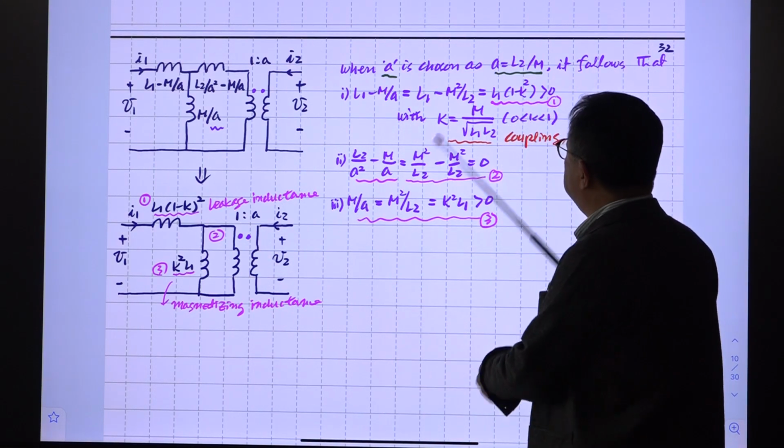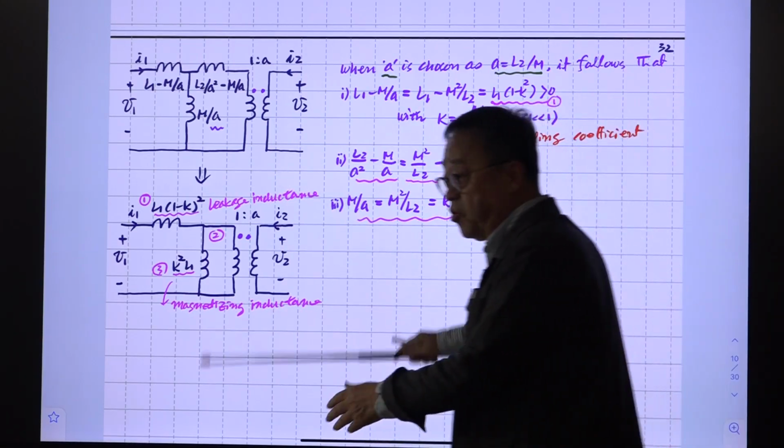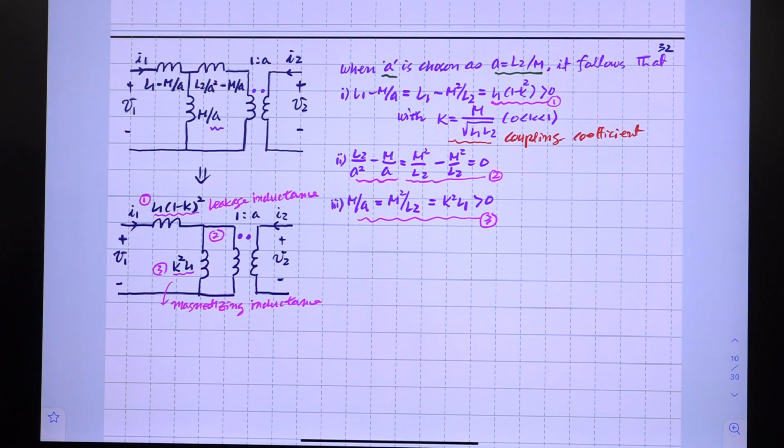So if you have this coupled PCB winding, this value will be different from the conventional transformer. Still the model works, right? Because we start out from the very general coupled inductor model, which can model any two-port network, right? But we come up with this number. So if we know this number, then we can analyze the circuit like we have some strange transformer in between, right?